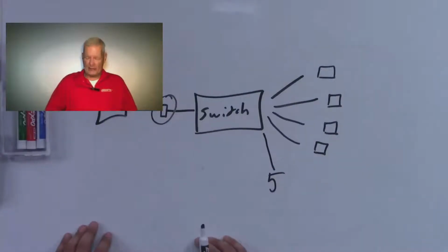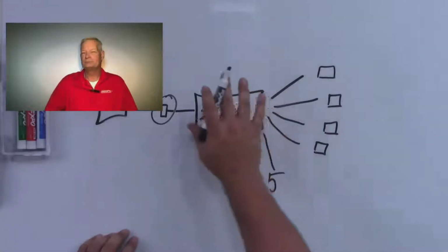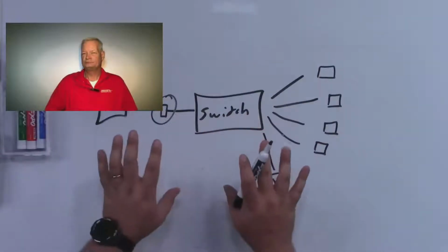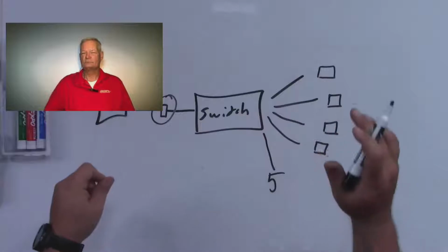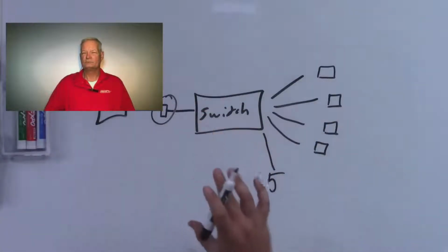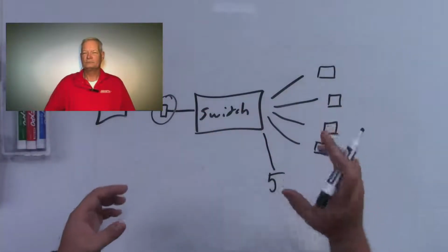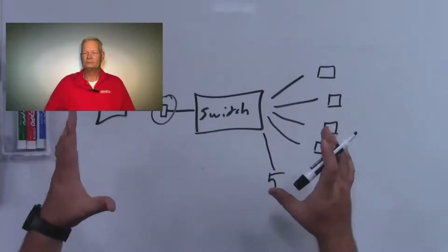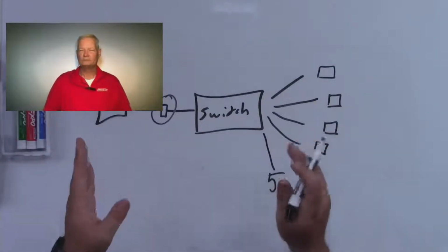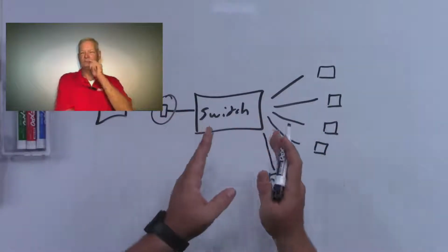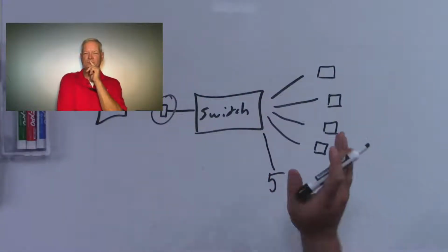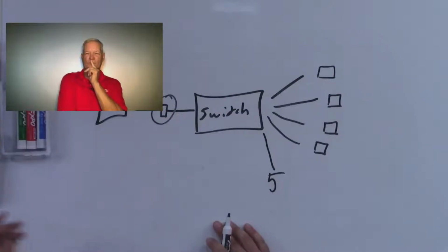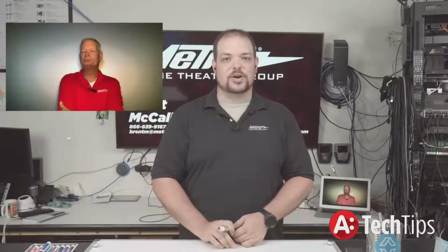If you have one display. Now, again, a lot of times a switch or a splitter is perfectly fine to have in there, because that works when you have one source and multiple displays, or one display and multiple sources. The problem is that if you have the need for multiple sources and multiple displays, do yourself a favor. Less devices in the signal path will ensure that you have the stability for an HDMI connection. Less is more. Less is more, very much so.